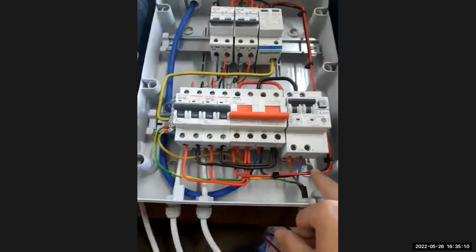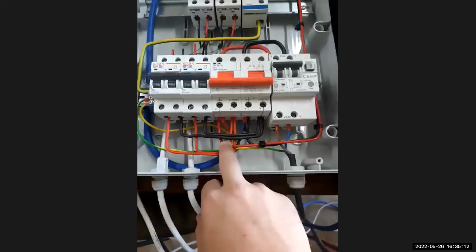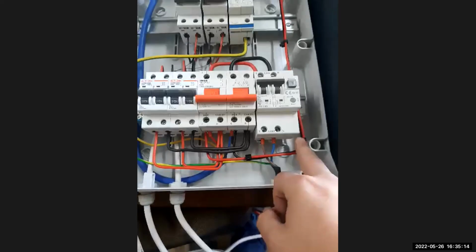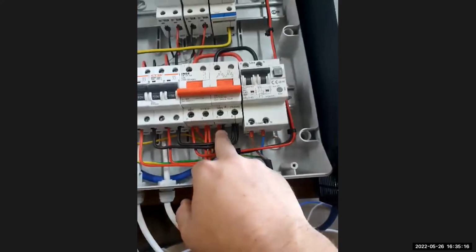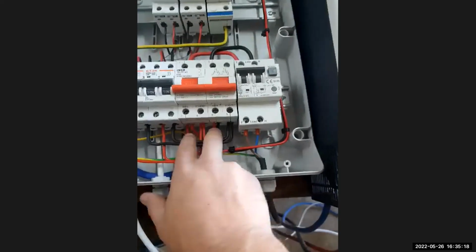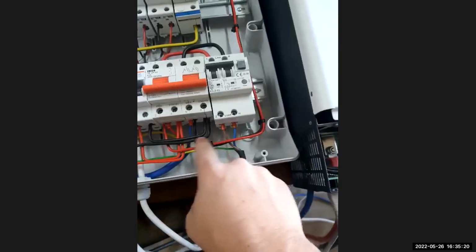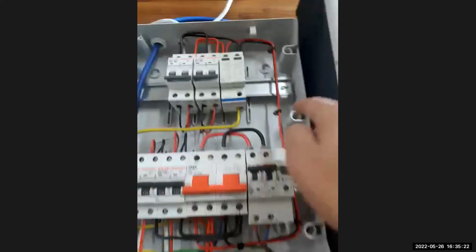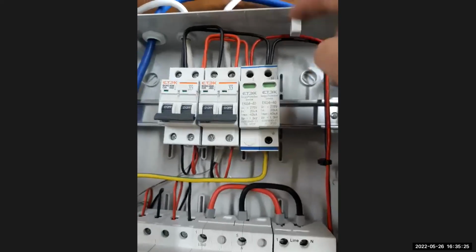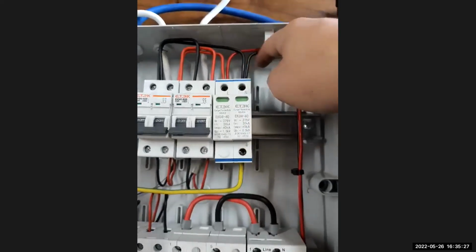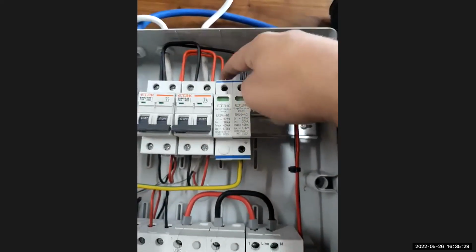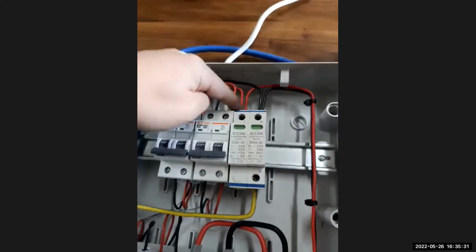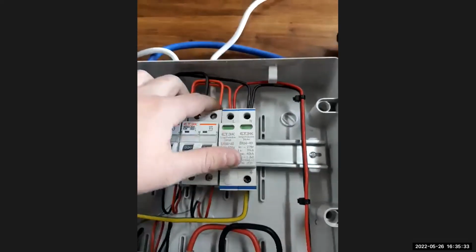Then the AC connection, you'll see I pull the AC connection also at the bottom of my changeover switch. From Eskom it comes in here and there, and that's where I pull my live and my neutral. Then it runs all the way to the top of this side. Now on my SPD, I bring in my power and it jumps over from the SPD to the first one and from the first one to that one.